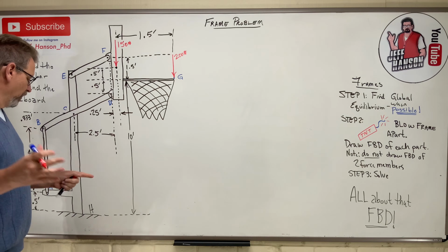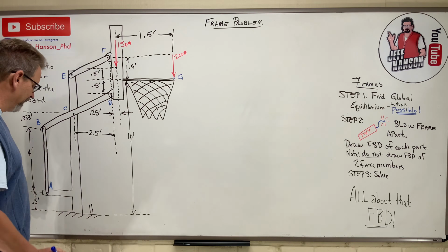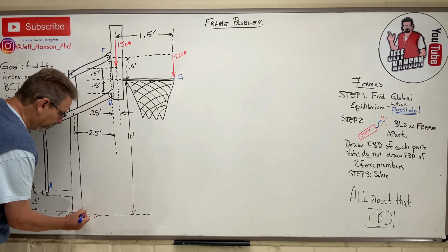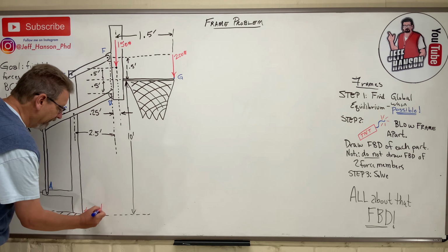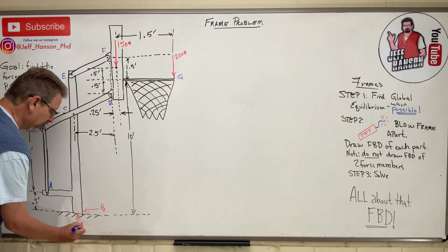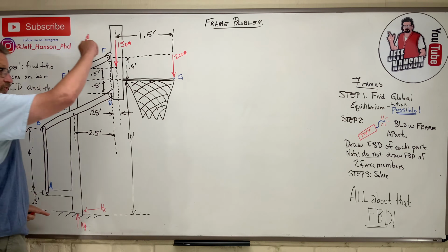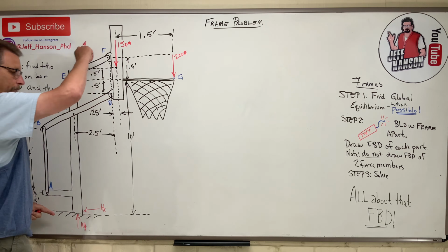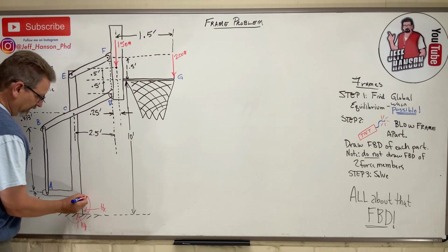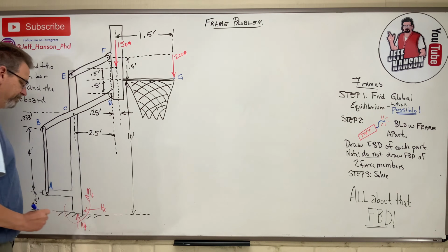Okay, are you back? Here we go. What is that? That is a fixed connection. It's like a cantilevered beam, right? So it has the following reactions. Okay, it would have a HX, HY. And then all of this stuff is trying to rotate it clockwise, right? It's trying to bend it over clockwise. So the ground's going, I got you, dog. And it's like doing that counterclockwise. We'll call that MH, okay?